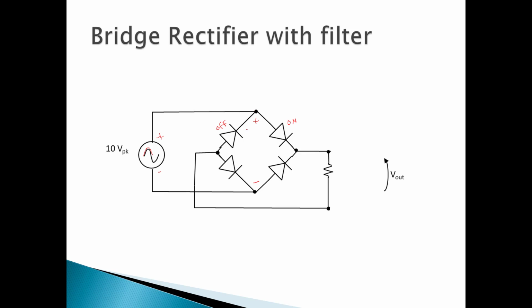Okay? Now we don't know about this point yet, so let's keep going around here. So if this diode's on, then that means this point is positive minus 0.7 volts, right? It took this value and subtracted 7/10 from it, and there it is. But it's still positive. So that means this side is positive, so this diode is off.